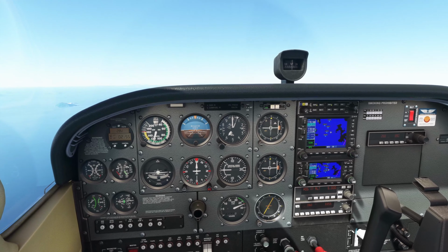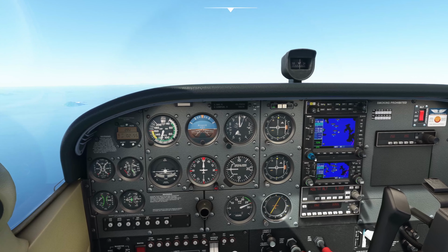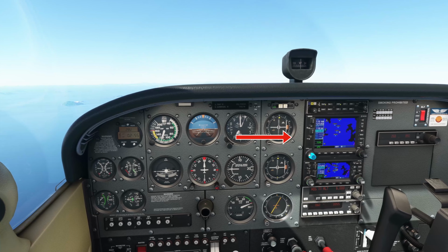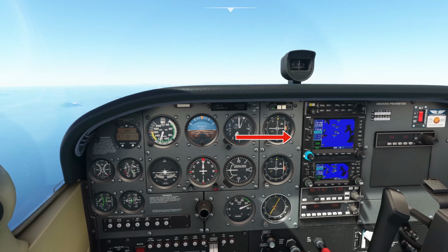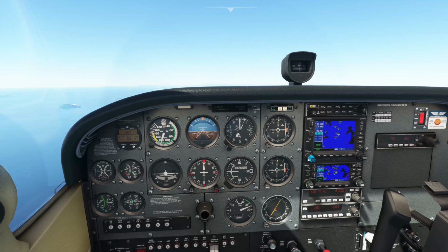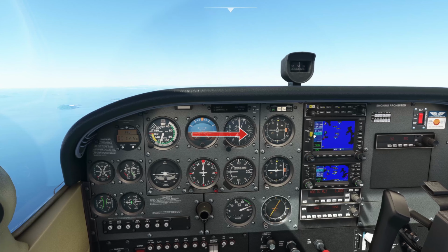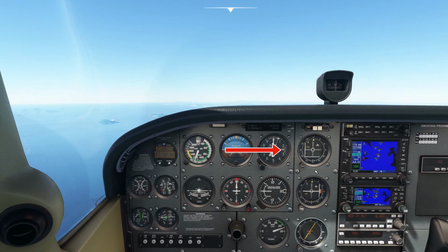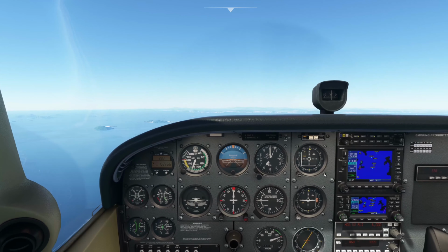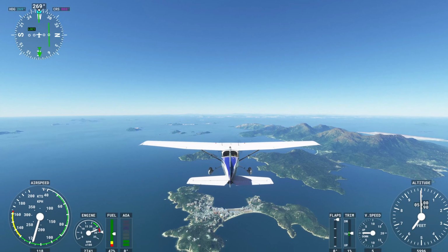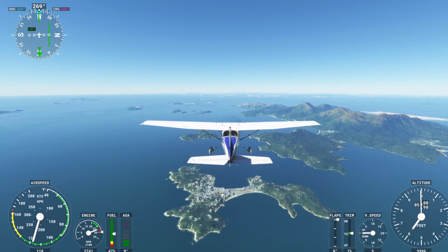Now for the ILS approach setup. The frequency of the ILS approach is 111.9, so this is set up in the VOR localizer section of the Garmin 530, and we then transfer this to live. We won't be using this until closer to the final approach, but you can see a reaction in the two bars immediately. We have the majority of the approach setup complete.